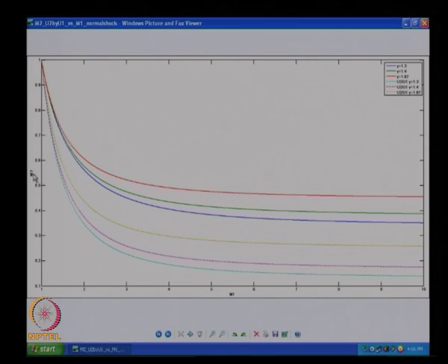where we saw that if I look at downstream Mach number as a function of upstream Mach number for a static or normal shock that is stationary, then as I increase the incoming flow Mach number with respect to the shock, the downstream Mach number decreases from close to 1 to something very low. But as we go to very high Mach numbers, the downstream Mach number tends to become a constant. It becomes an asymptotic value, different for different gamma values which we have here.